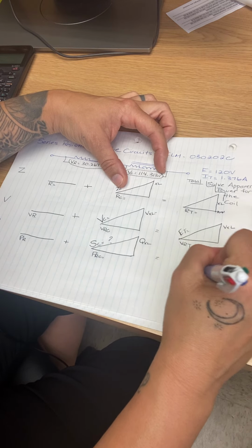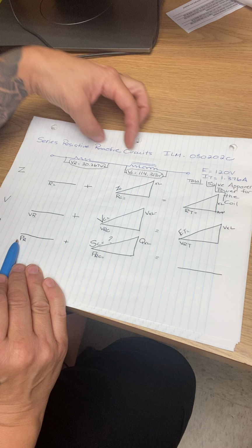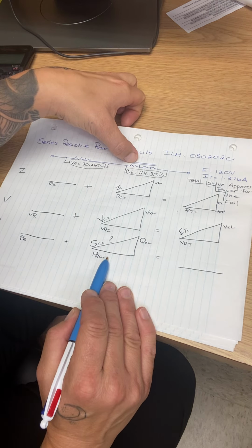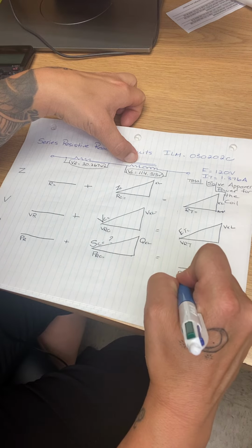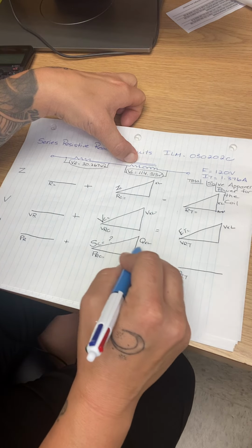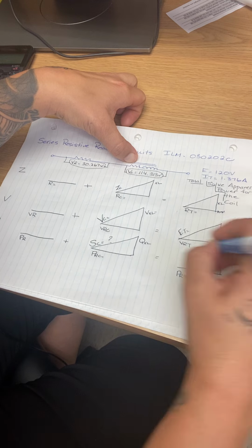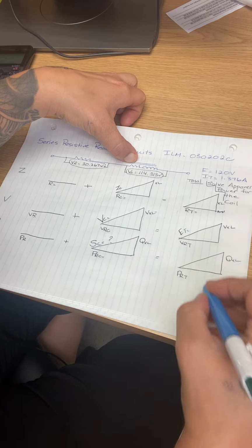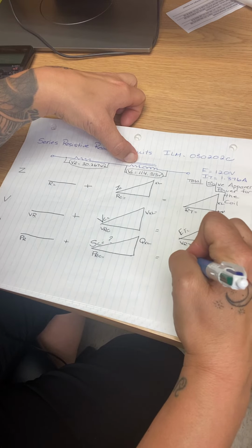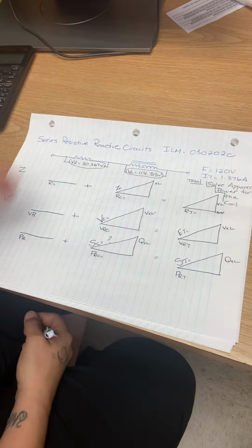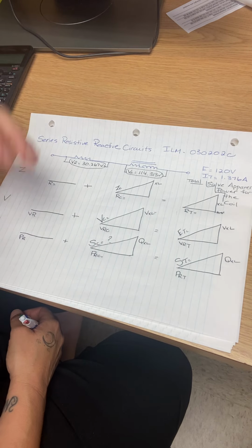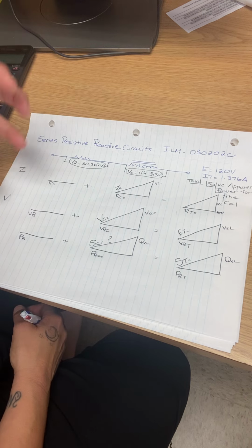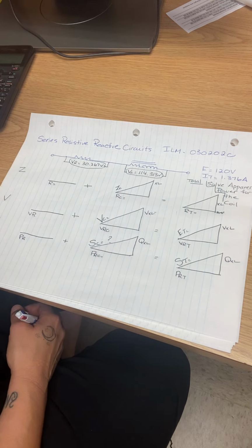Okay, and then the triangle total, so the power that's dissipated in the resistor is in phase with the power that's dissipating for the in-phase component of the coil. So that would result in PR total. And then whatever reactive power is being produced from my inductor would then just carry forward over to my circuit total. And then the vectorial sum of those two sides would be my S total, apparent power of the circuit. So yeah, I'm not going to fill in every value for every triangle component because I don't have to, but it allows me to see the connection between all of the variables.